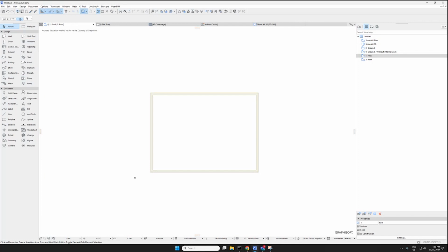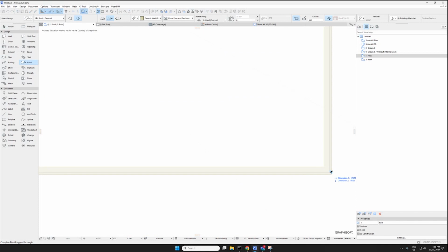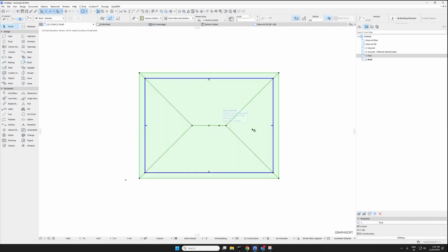We've got obviously the hip roof, the gable, skillion, and so on. So I'll show you different ways you can draw a roof. Go to a standard roof. I'll click there, and it's automatically chosen a geometry method, multi-plane roof. And we'll select the external walls, and it's drawn a roof for us there. And this is a traditional hip roof.